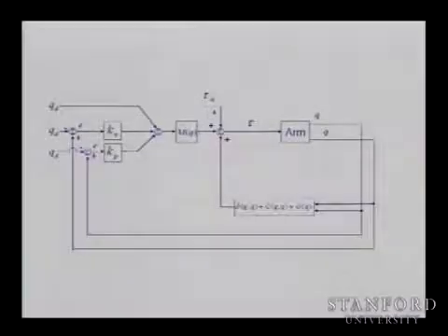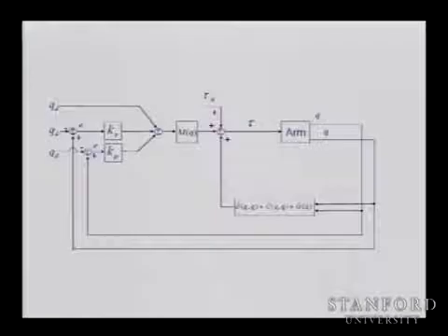So this is the overall control system. Basically what we are doing is we are doing a feedback that is compensating for centrifugal, Coriolis, gravity, and all these forces. And then we are scaling our input. So this is torque prime. It's scaled by m hat, and we are adding these to produce the torque.